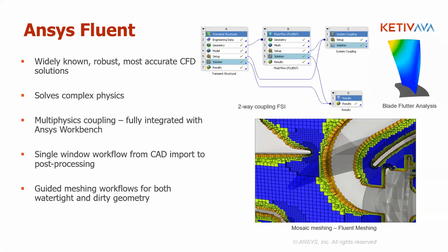And when I say that, I mean that the number of cells, the mesh count, is optimum enough. It's not over refining. And the second part is that because the mesh elements, their shape, their skewness, their orthogonality, the quality of the mesh is so good that you don't have to worry about generating a good mesh. The solver takes care of that for you. It'll auto-generate a mesh that will give you the best possible, most accurate solution, which is what you see on the right over here.